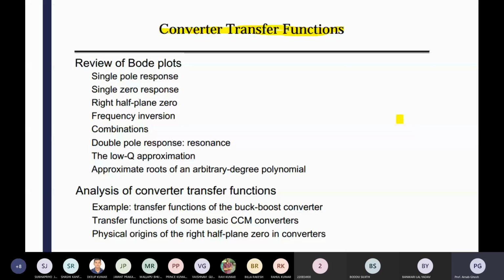Your input variation is 50% of your reference input value, meaning the input value you have designed for the converter is 5 volts. Now your input value is 5 plus 50% of 5 volts, meaning 2.5 additional, so 7.5, but your output is still coming perfectly at 12 volts. So you can say that your converter is robust. Same thing for plus minus 50%.